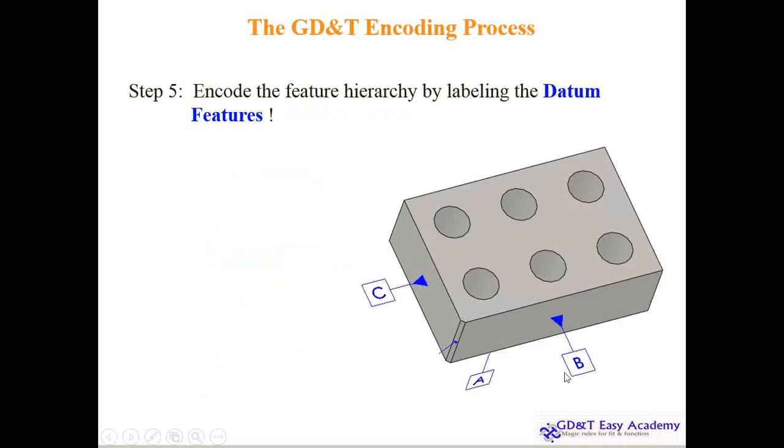This is the encoding. The A is the bottom of the plate. This A, which we are seeing, is the bottom of the plate. And intentionally, I am giving a 2x2 chamfer here to show that an unsymmetric part can be toleranced by GD&T in a symmetric way. And earlier we saw a symmetric part toleranced in an unsymmetric way. That is the biggest headache.